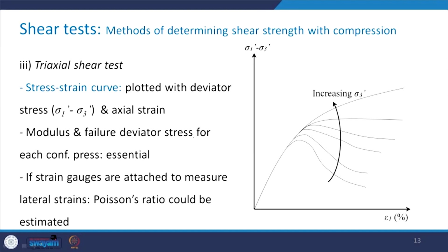increasing the axial load, and directly it is going to give you the stress versus strain response, and from there you will be able to analyze those test results to get the shear strength characteristic of the rock specimen. See how? See here, this is, as I mentioned, that stress strain curve.